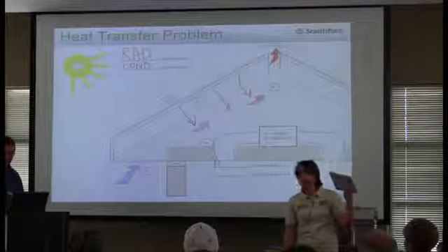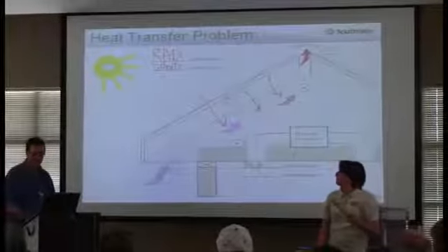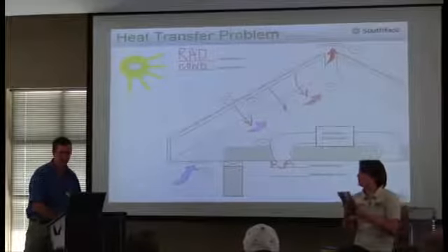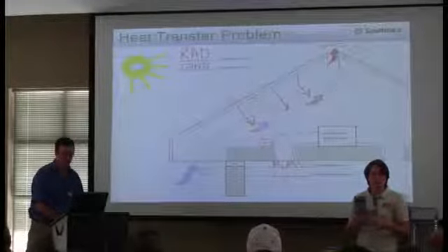Question? Do you have a question? You don't recommend doing spray foam over a product like that? Not over that. No, it's kind of one or the other. You can't spray foam on top of this. Can you do baffles and then spray? Yes, you could. But it's probably...